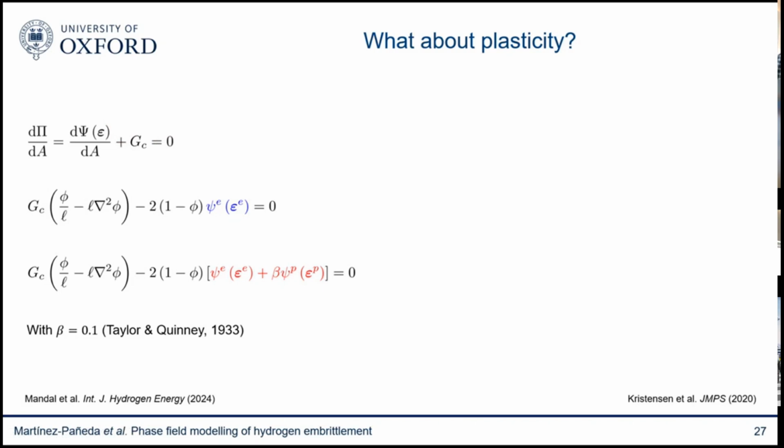So that's one thing. But then there's another thing. Of course, thermodynamics holds, the energy balance still holds. In principle, you can apply the method as it is to plasticity. But there's one additional aspect. We said our driving force of fracture, before we were talking about the elastic strain energy density, is the energy stored in the material, right? That's what thermodynamics tells us. So it's the elastic strain energy density.